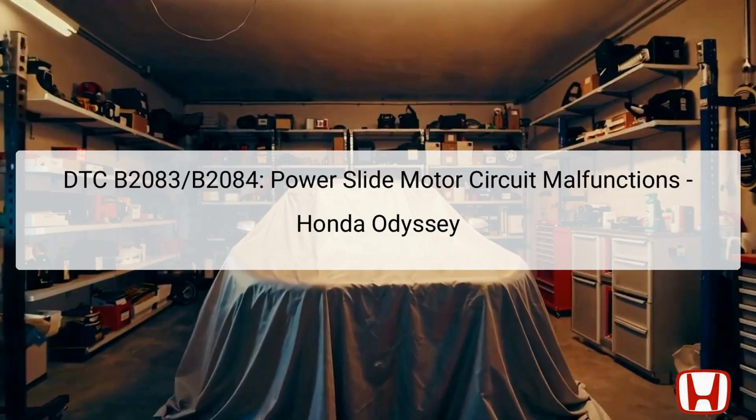The Diagnostic Trouble Codes, DTCs, B2083 and B2084 are associated with the 2011 to 2017 Honda Odyssey's right power sliding door system. DTC B2083 indicates a malfunction within the right power slide motor circuit, which is essential for controlling the opening and closing of the power sliding door. Meanwhile, DTC B2084 refers to a malfunction within the electromagnetic clutch circuit of the same motor.